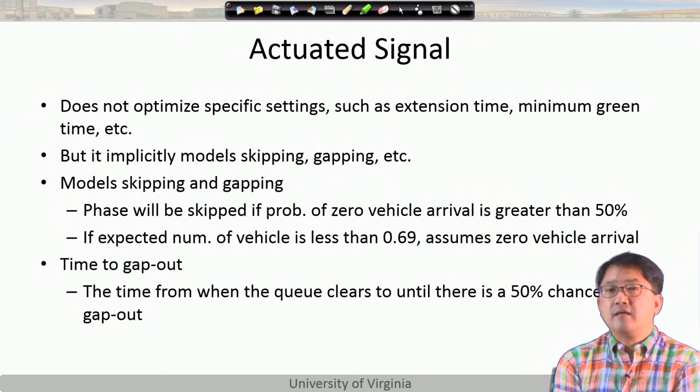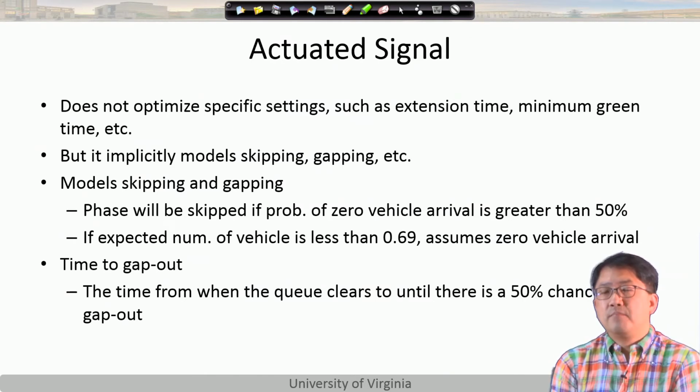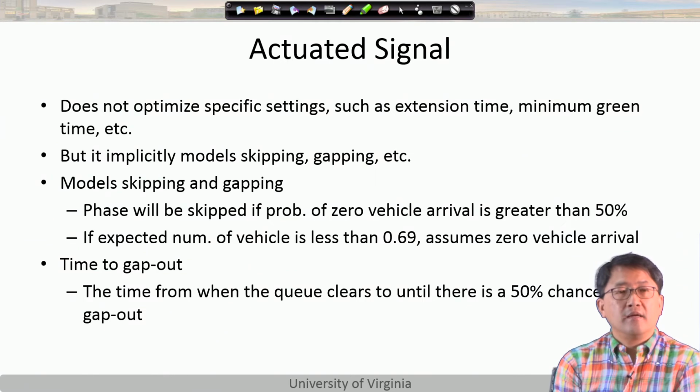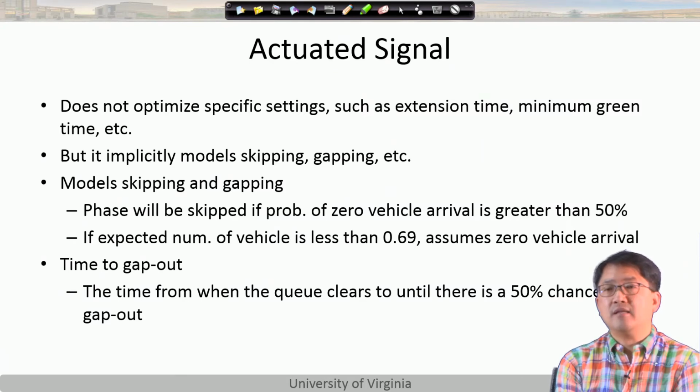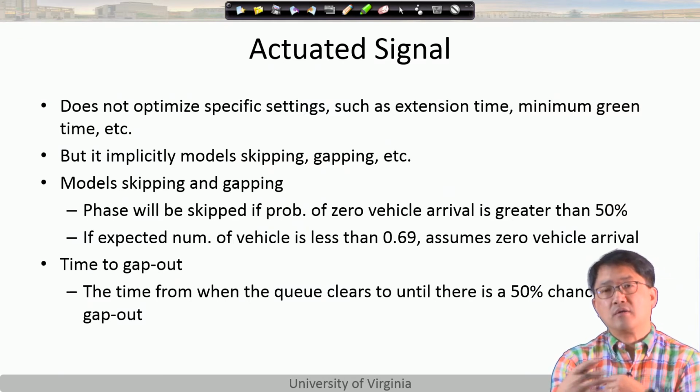But at least they consider this as simulating actuated. In the actuated signal, one good thing is possible phase skip. If there's no right turn vehicles waiting, then you don't have to serve right turn by providing 5 or 6 seconds of green time. They can do phase skip, it immediately goes to through. So through can have a longer green time for providing better service.